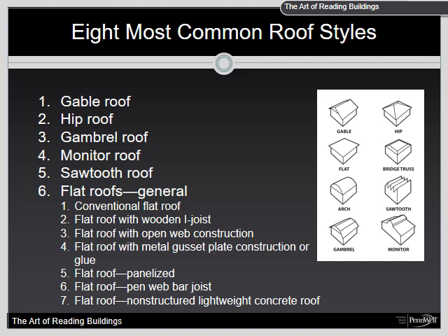Flat roof with an open web construction. Open web construction consists of top and bottom parallel wood chords connected by steel tube web members. Another version of this construction is all metal in the same configuration and is referred to as open web steel joist. In both versions, the top chord that is under load offers a bridging effect, causing it to be in compression, and the bottom chord, the unsupported side, to be in tension.